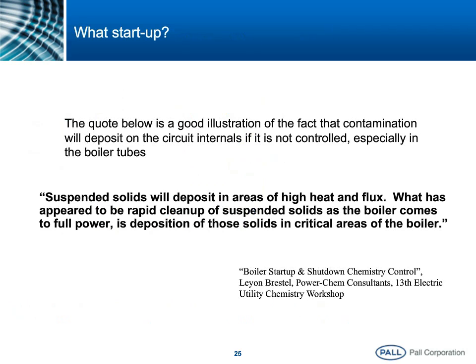And to that effect, I will just read the quote here from a utility chemistry workshop conference, that says, "Suspended solids will deposit in areas of high heat and flux." So let's face it, we're talking about boilers here. "What has appeared to be a rapid cleanup of suspended solids as the boiler comes to full power is the deposition of those solids in critical areas of the boiler."